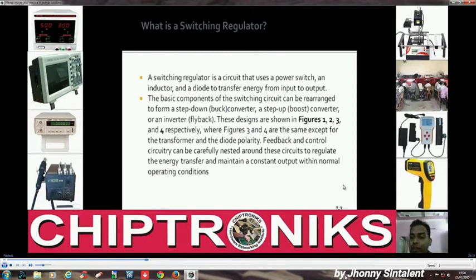Okay, so I think I'm pretty clear with what I'm saying till now. A linear regulator generates a lesser voltage through the loss across a resistor, whereas a switching regulator generates lesser voltages by controlling the turning on and turning off of two switches.